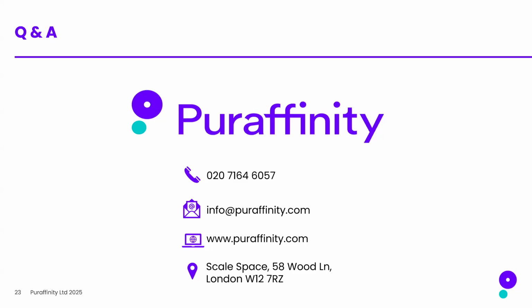I don't have any side-by-side data. Again, knowing what we know here and knowing the pilot studies out there, we would operate at significantly shorter contact times than that product. Can the product be used for highly PFAS-contaminated material like firefighting water from PFAS firefighting foam? That gets back to the high concentration question that just came before. And yes, in theory, but again, your frequency of changeout is going to increase.